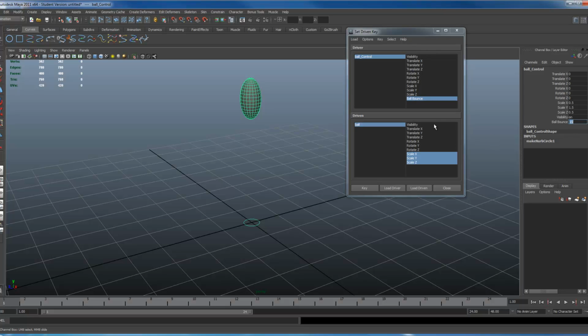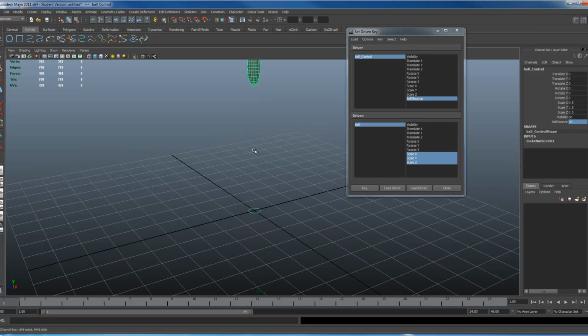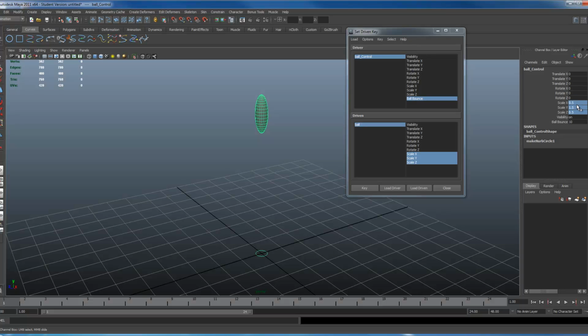So let's double check everything again. Let's make sure frame 10 looks proper. Seems like I didn't key on all of these, so again on all of that. I've been keying on the wrong values. Let me make sure I click on the actual sphere. And there it goes. Let's go to frame 5 again. Click on my actual sphere. That'll be a 0.5, 1.5, and 0.5. Let me key that.